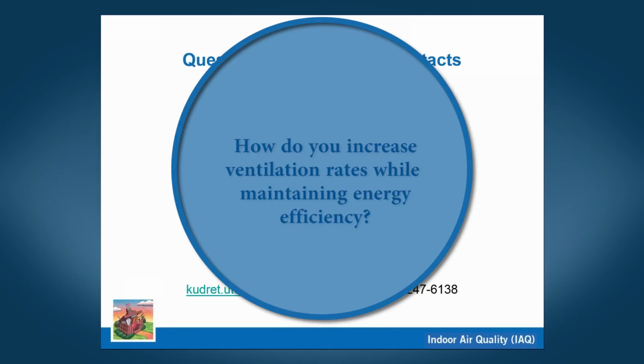So that doesn't directly answer it, but these are things to look for that would help you no matter what. Another one would be building static pressure. If you're pushing more air into a space than you really need to, and you can find this out either through commissioning or checking with engineers, a lot of that's going to leak out of the building anyway, and it might also cause your exhaust dampers to open when maybe they wouldn't otherwise do that.